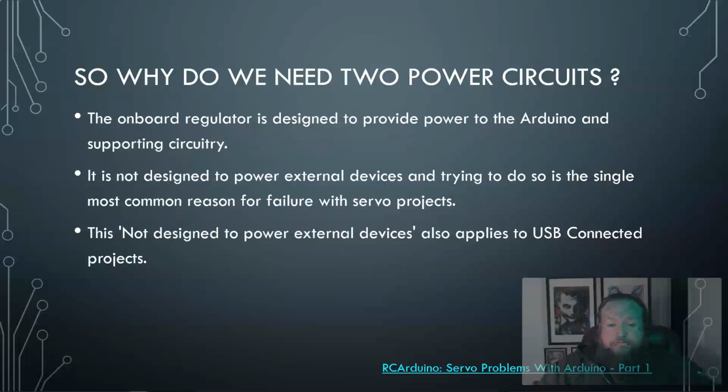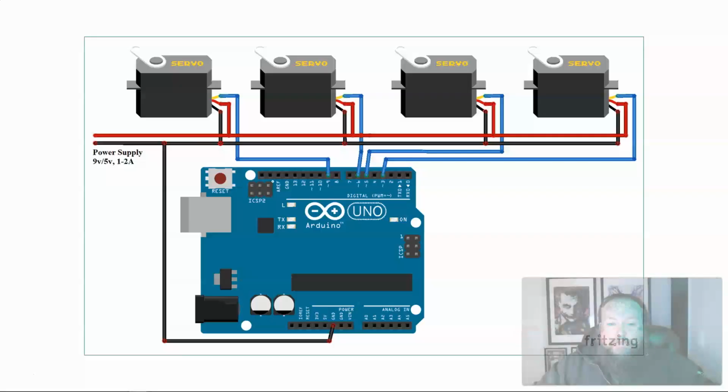So those are the basics from there in that USB, but you'll get more something like this. Why I want to jump ahead quicker here is, say, examples that you could get something that's hooked up this way. You'd have the Arduino Uno, and you have a common ground shared here with each servo's 3 pins, black here being the ground. They're all connected to the ground for the external power source, and this ground is also connected in some way from the Arduino to that same common ground.